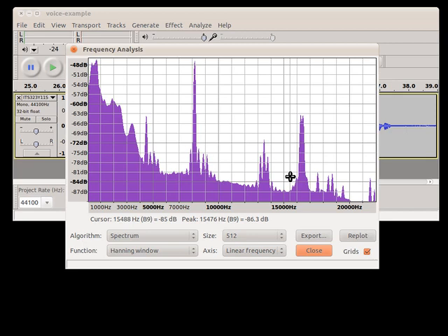The frequency components of the input of this original analog signal were around 0 to, let's say, from our plot, 20 kilohertz. That is, from this plot, from 0 up to 20 kilohertz. But in fact, most of it finishes at about 3 kilohertz. That's the frequency components, or the spectrum, of this analog signal. It comes to the wireless transmitter. What this does, one option would be to transmit as is, components ranging from 0 to 20 kilohertz to the wireless receiver.